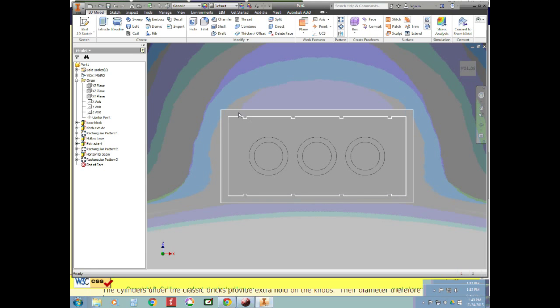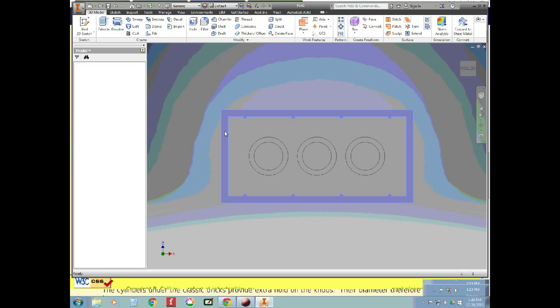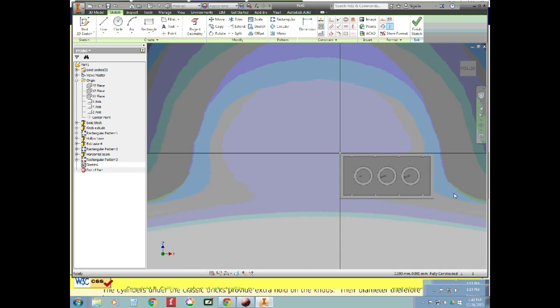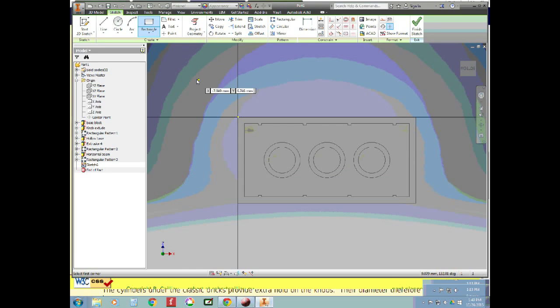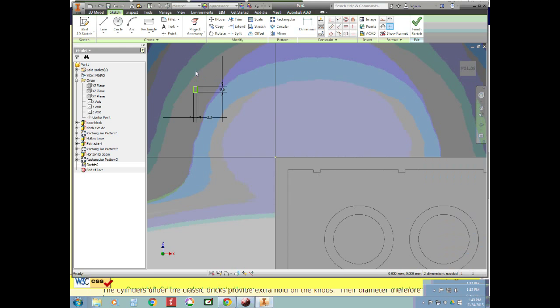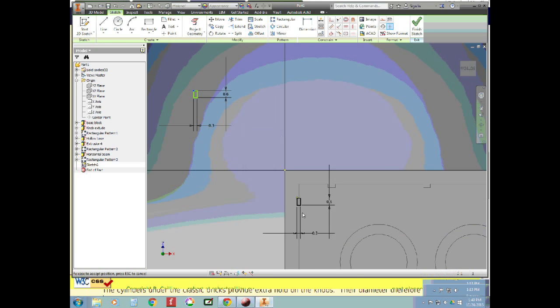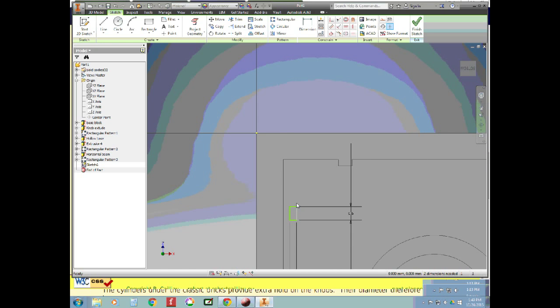Okay, so once again, create a new sketch. I'm going to right click, new sketch. Draw my rectangle up here. It is 0.3 wide by 0.6 tall. Turn off my constraints by pressing F9 so that I can see what I did. Bring it down to my drawing. And once again, we got to constrain its position. And there we constrain the midpoint of this line to this line. So we went up here to coincident constraint, which allowed me to grab this midpoint and put it here.